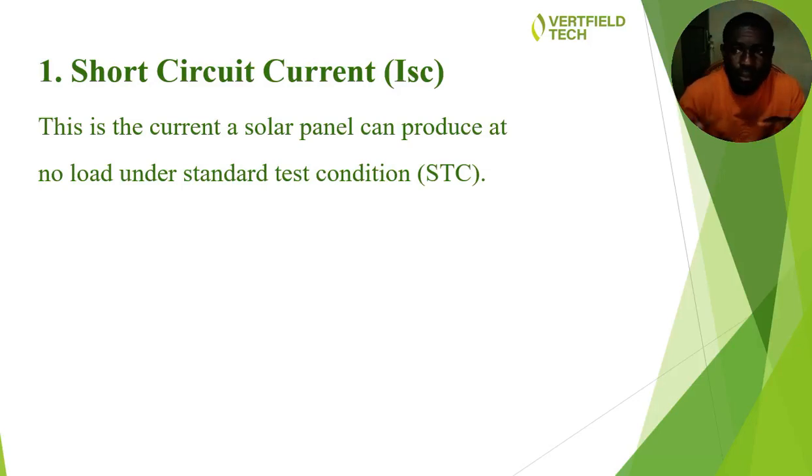No, there is no cause for alarm at all. What you need to know and understand is that, due to the fact that it might be early morning when you are about to start the installation and you're taking this reading, it might be that the solar panel has not fully woken up. And as such, it might not be in a good shape to give you the full or complete ISC that is required.